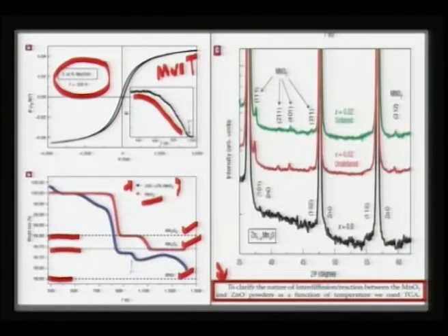So you are almost getting a similar feature to that of MnO2 in zinc oxide, but the formation of Mn3O4 here is above 1000 Kelvin, whereas that region is actually more favored even at low temperature, as low as say 980. So, there is a considerable shift in the formation of the second plateau, that is Mn3O4.